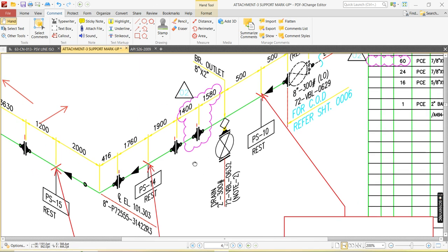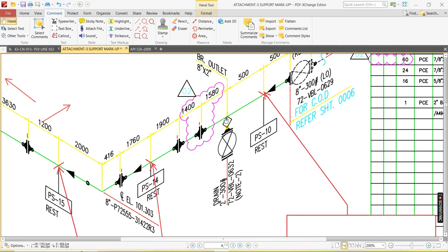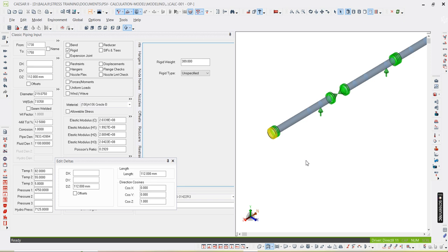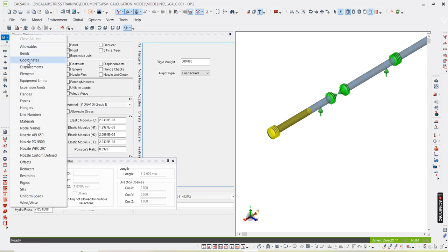After that you see the same one spool is there, again two flanges, again on spool is there, two flanges. So instead of modeling one by one, you can model each element like this, what we have followed. Or you can copy this and you can check. You can copy and paste also. I will show how to copy and paste. Here you can select like this, this portion only, and duplicate. You can do like this also. Or go to this, this is list input and elements.